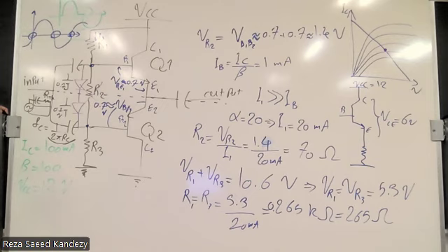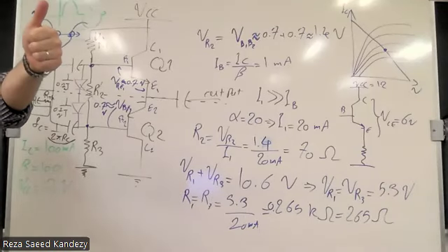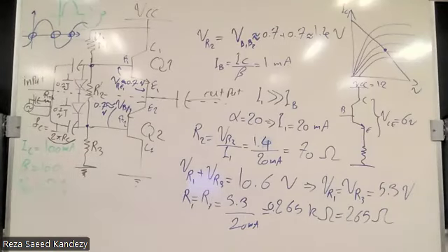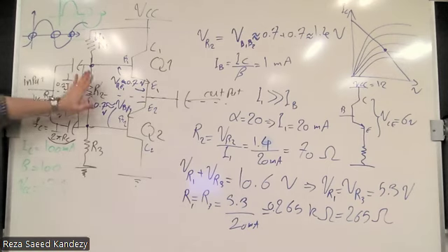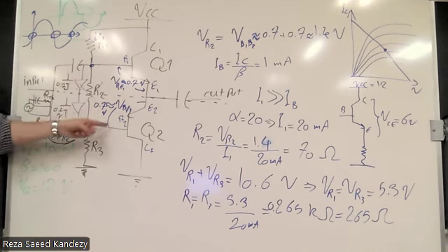So when we add those two, they just give a voltage drop and we recalculate R1 and R3, and we still get the same. You're going to still get the same because before, first of all, did I answer your question? Yeah. Before, when we didn't have these diodes, we designed it for the ideal case, where these two are 0.7.